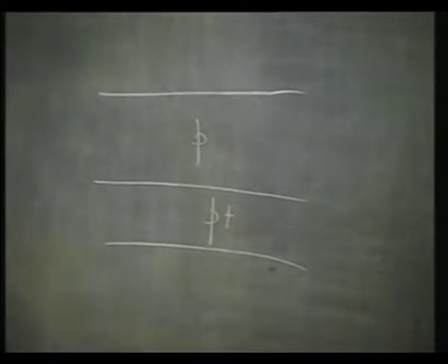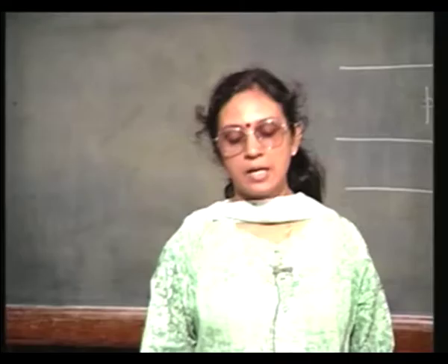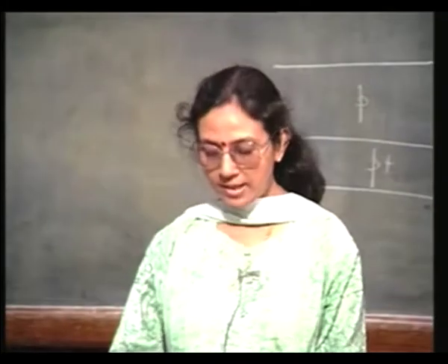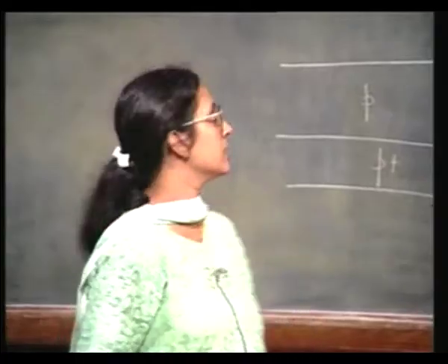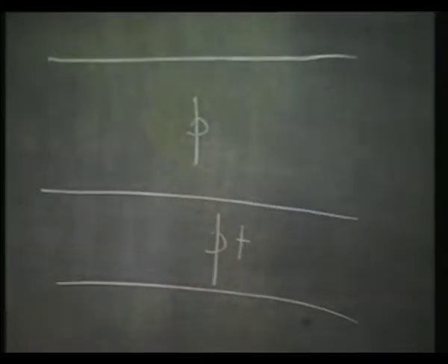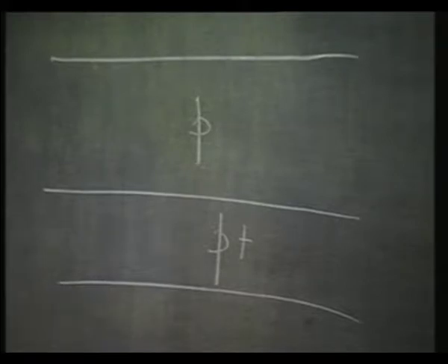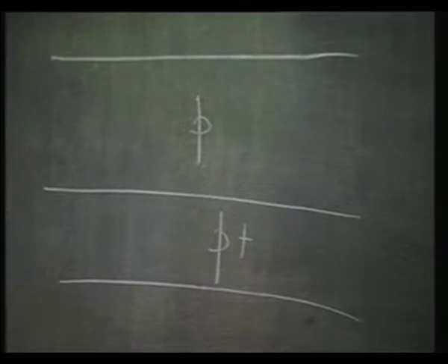Now, in order to realize a CMOS device in this, you must have an N-well. I already have the P type substrate. So, actually I am talking about an N-well technology which is compatible with the NMOS process flow. So, I need to have an N-well in this. Okay.